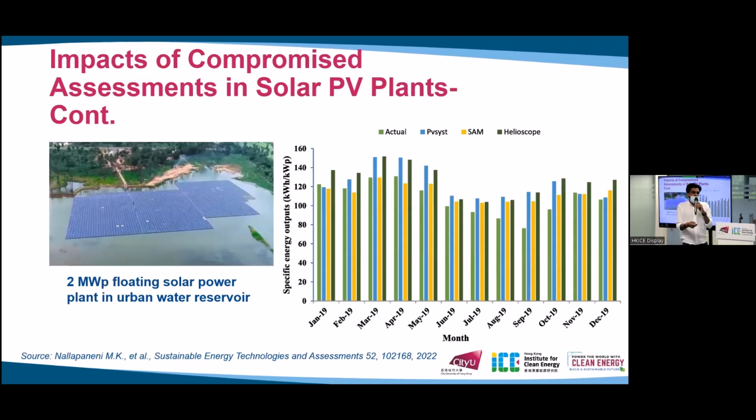Now, if you see the effect of simulation tools, we did this simulation study considering a 2 megawatt floating solar power plant installed in an urban water reservoir. We also have a similar plant in Hong Kong. Mostly, industry people use tools like PVSyst, SAM, or Helioscope. They use these tools to give the performance data and estimate the revenue potentials, and with this, the client would generally say yes or no for project installations.